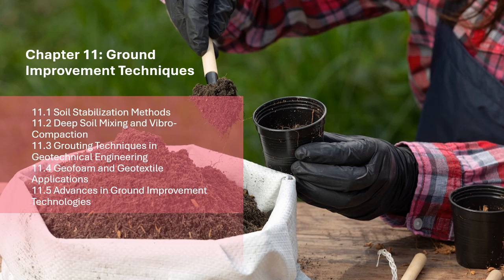Feature: deep soil mixing, DSM; vibrocompaction. Speed of application. DSM is a slower process due to mixing and curing time. Vibrocompaction is faster compared to other techniques. Cost. DSM can be more expensive due to binder costs and machinery. Vibrocompaction is generally cost-effective for large-scale projects.